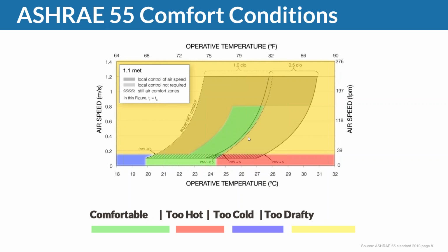That's just a very high-level overview, because there are other factors at play, such as radiant temperatures, and the insulation, so what clothes the occupants are wearing, etc. For today's session, we're not looking at these things. Also humidity, right? We're not going to look at the details of that, but rather get a rough overview of how this works and how customers on SimScale are simulating such HVAC systems to check for ASHRAE 55 compliance. So not going too much into the details, just getting an idea what this color scale means.